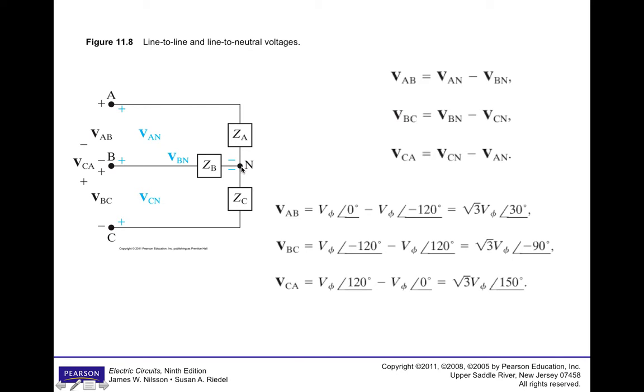What's not shown here is that from this capital N at the load end, there is probably a wire connecting that to the generator N, which would be the lowercase n. That's not illustrated here. Since it's only a wire and it's considered an ideal conductor, it's only a node anyway. So the voltages between each line, A, and the neutral are what we refer to as line-to-neutral